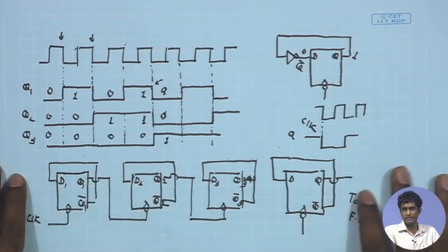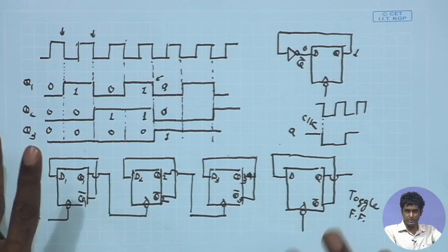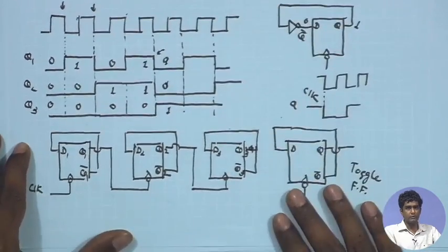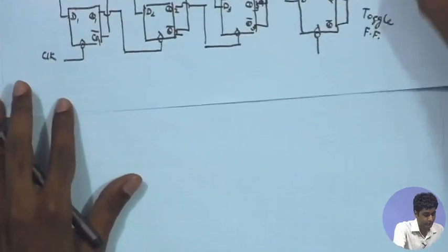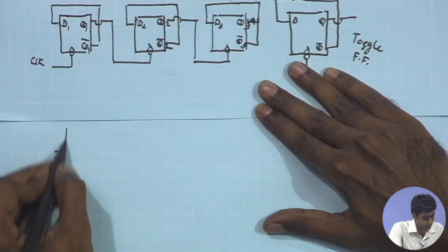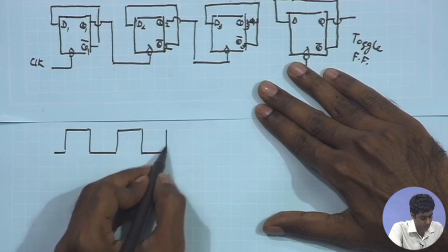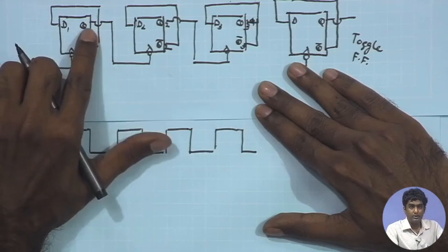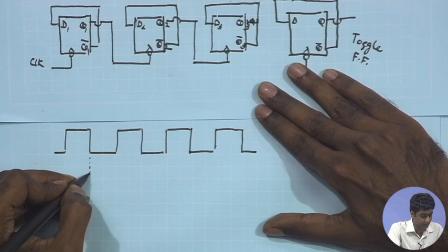We know that digital circuitry, whenever we are talking about CMOS digital circuitry, inverters or any digital logic block, they have their own inherent delays, and therefore, if I look at the waveforms corresponding to this arrangement, we have the original clock coming over here, and the Q1 is going to have a delay with respect to the negative edge of the clock.